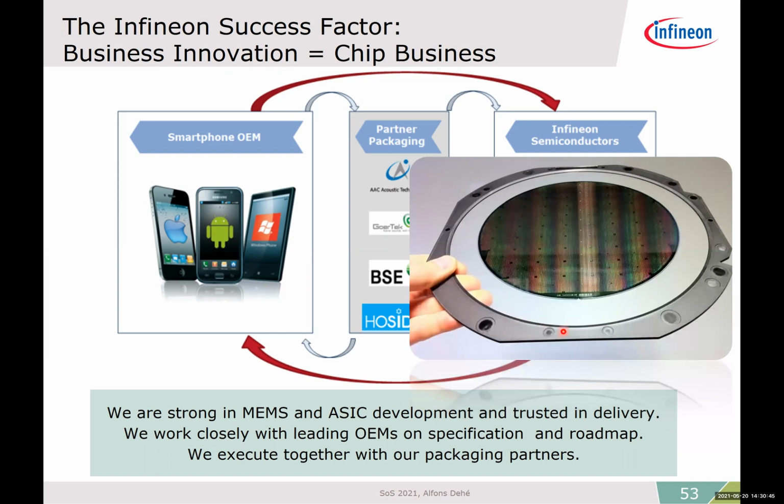By the way, this is a wafer of microphone chips. This 200 millimeter diameter, and I believe this 25,000 microphone chips on it. And this is the form factor. You have here, I hold a frame and the dicing foil, and we have the diced microphone wafer on this. And with this, you ship this to the packaging partners, and they pick the microphones into their package and stuff like this. We will see how to fabricate this later.